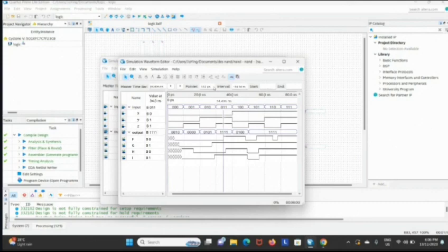By comparing the delay time of both designs, we can say that the NAND network would be better to use in this system, as the delay time has been shortened, which means the response time is faster. For example, the delay time for the NAND network is only 4.496 nanoseconds, which is 0.176 nanoseconds less than the simple circuit design. With a shorter response time, the system can function faster, and it may help to extinguish the fire in a shorter time, reduce the loss, and save more lives.